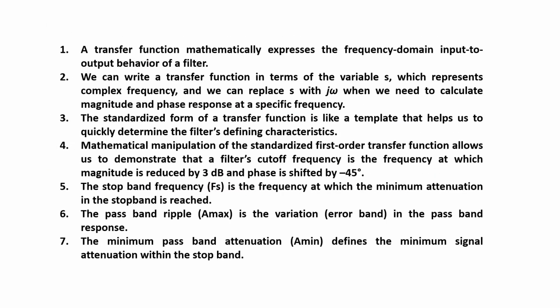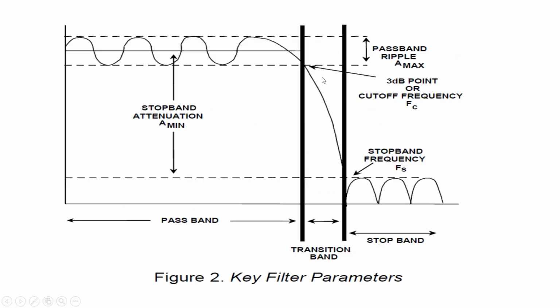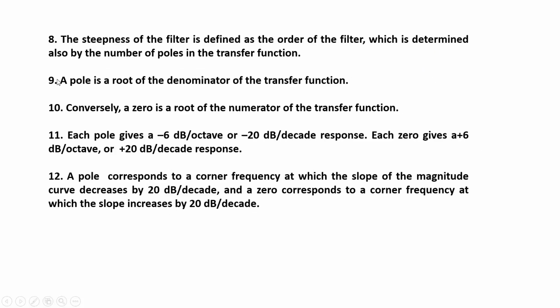See here, this is the cutoff frequency. It is the minus 3 dB point for a low pass filter, and the power corresponding to this frequency is half of the DC gain power. That's why this point is known as the half power point.